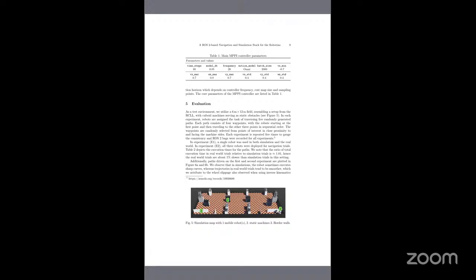So that's why this is called an omnidirectional robot. Because of that, we should select the Omni motion model. Batch size 2000 means every controller cycle checks 2000 different trajectories. Then, based on the 2000 different trajectories, select the appropriate one, choose the best trajectory. So this was one of the major advantages of this MPPI.